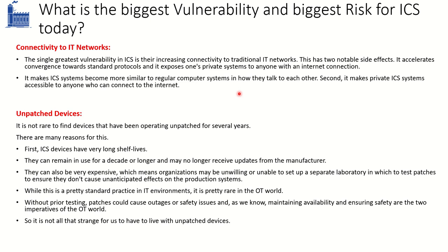So all these different projects that are running currently in the ICS environment demand the ICS environment to be connected with the IT networks. And now when you are connecting the ICS devices with the IT networks, the vendors are also manufacturing these devices taking these requirements into consideration. So 10 years ago, 20 years ago, you would not have seen a scene within an ICS environment where a PLC was connected to the network and had an IP address. But now, this scenario is very common where you would have a PLC connected to the network. It will have an IP address. It will be operating on standard IT protocols.